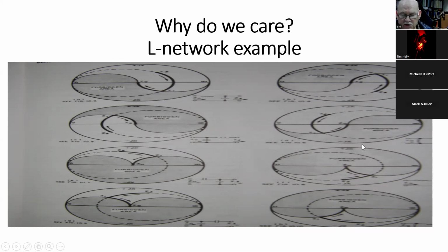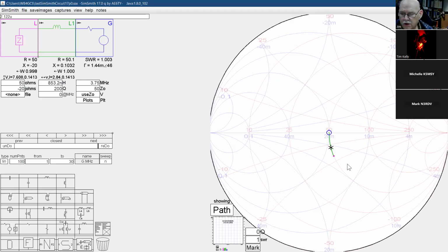By keeping these things in mind, and I wish to God the ARRL published them somewhere, and like I said, we'll have this published, and if I find a cleaner presentation, I'll make that available, this knowledge allows you to develop a strategy to deal with how I'm going to get from an impedance, say here, around to where I want to be, which is 1 plus j0. And that's the object of the exercise.